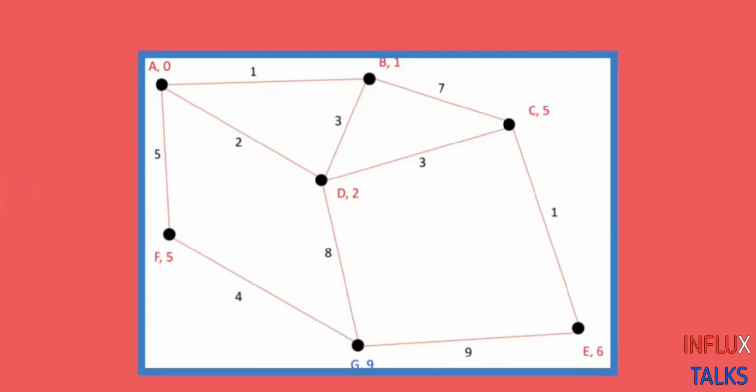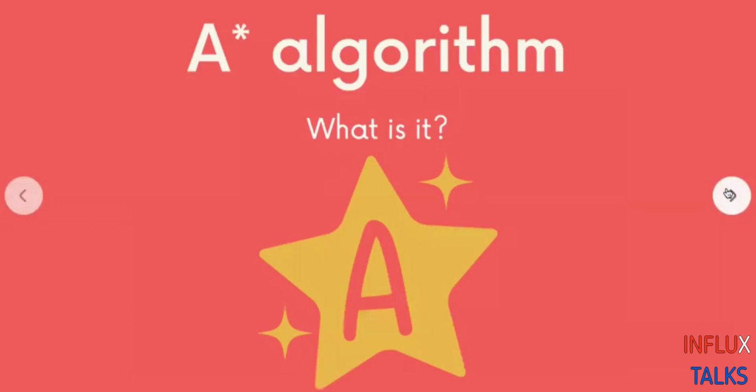And since it can also incorporate the cost or distance of edges, it is considered to be better than Grassfire. Our third algorithm is A star, which is the most important algorithm in path planning. When applied on a grid graph where all of the edges have the same length, Dijkstra's algorithm and Grassfire algorithm have similar behavior. They both explore nodes in order based on their distance from the starting node until they encounter the goal. A-star search attempts to improve upon this by incorporating something called a heuristic function that guides the path planner.